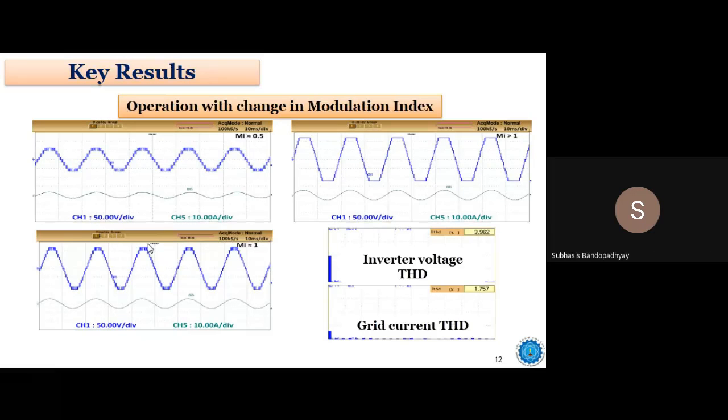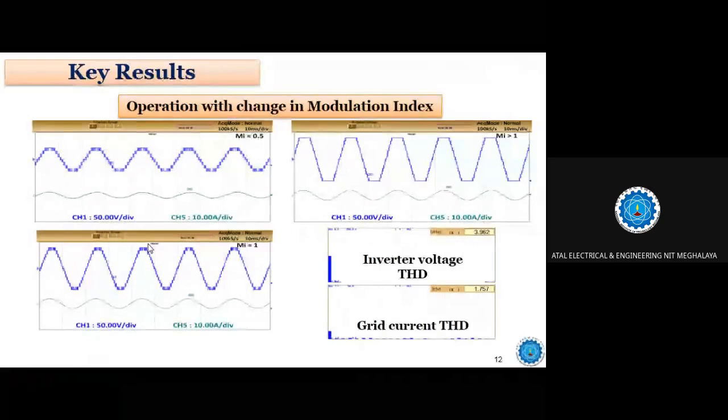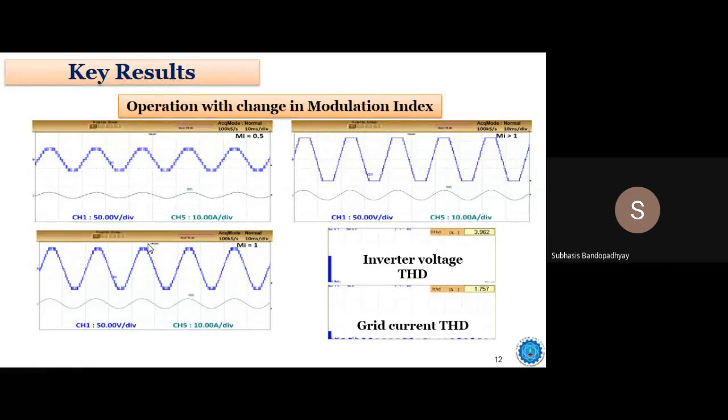Yes, that angle is cosine of that theta. If we are increasing, if we are taking theta, meaning the number of harmonics, cos theta 1, cos 3 theta, cos 5 theta, odd numbers up to 11 and 13, in that case how will be the sequence of that firing angle?